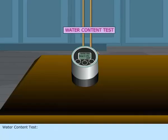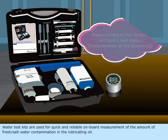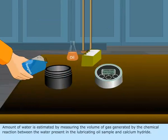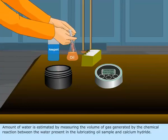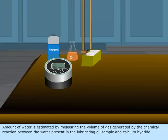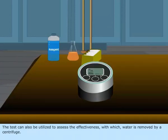Water content test. Water test kits are used for quick and reliable onboard measurement of the amount of fresh or saltwater contamination in the lubricating oil. Amount of water is estimated by measuring the volume of gas generated by the chemical reaction between the water present in the lubricating oil sample and calcium hydride. The test can also be utilized to assess the effectiveness with which water is removed by a centrifuge.